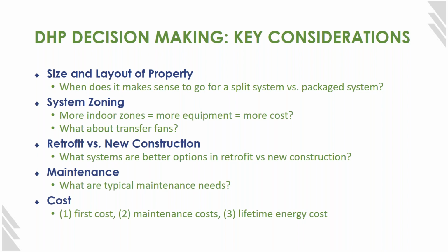For a package system, maybe if you don't have patios and you have a taller building, where you would locate the outdoor unit for upper units or lower floor units might be tricky. You might consider going with a package system. And then if you want to do a split system, but you have a very tight site and it's a taller building, and you have very small units, maybe the VRF system would work because you have a smaller number of outdoor units to serve the whole building.